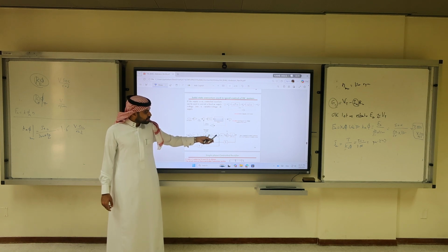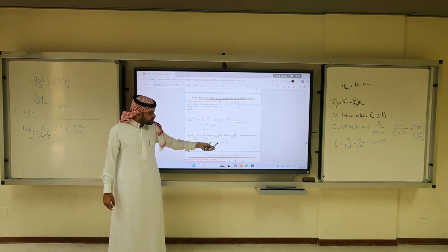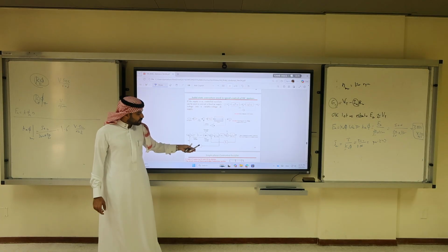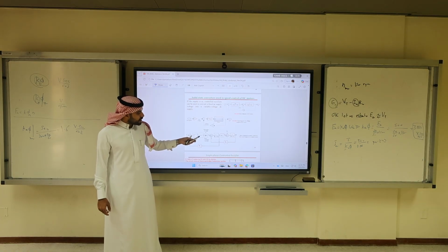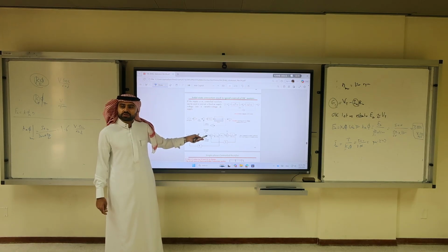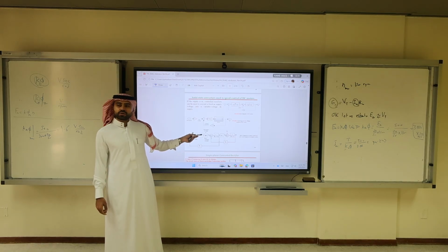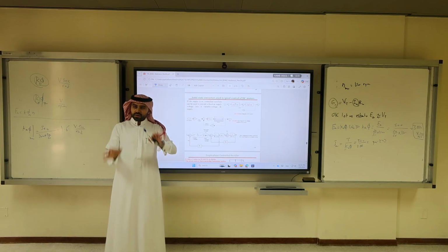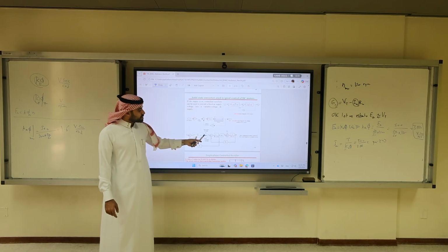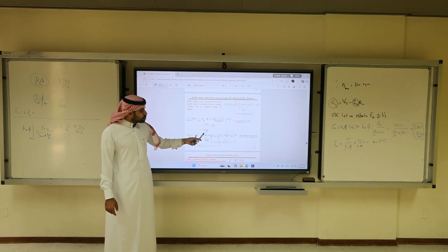Here we take the current, we measure it, we multiply it by a constant, we put it into a current limiter, we take the cosine inverse, we get the firing angle, and we apply it to power electronics. We don't have power electronics in the project. We have a current limiter, but not power electronics. So this is another system to apply the control.